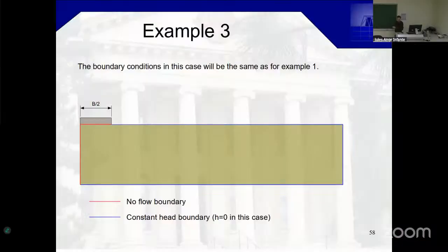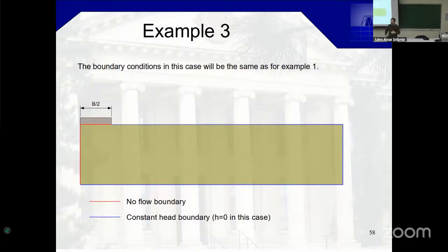So last time we had left off working on this, which looks a lot like the 2D example that we saw right before. The week before, we had done a 2D example, which was basically a cut through our domain. And we had exactly the same boundary conditions, if I remember correctly, right? No flow under the footing, or half the footing, because we were using symmetry. In this case, it's axisymmetry, so we will always have a no flow boundary here at the axis of symmetry.